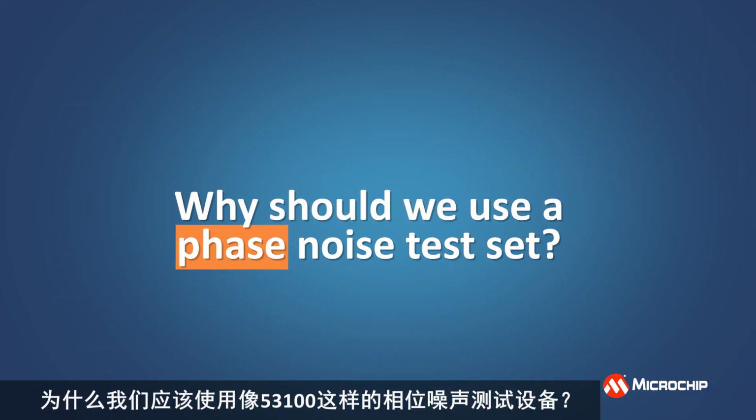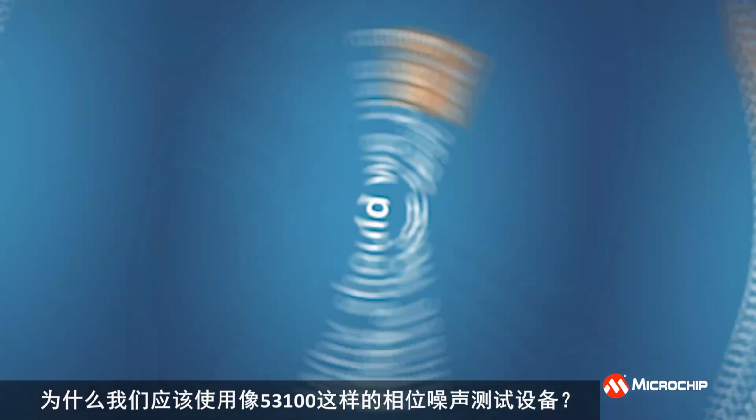So why not take these measurements with an oscilloscope or, say, a spectrum analyzer? Why should we use a phase noise test set like the 53100? Well, an oscilloscope really works well in the time domain.